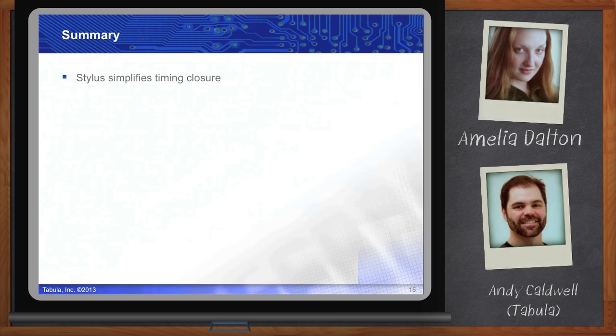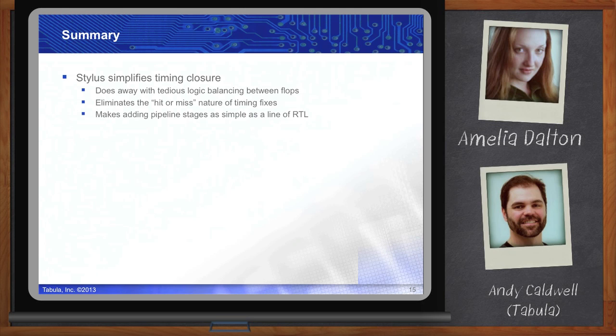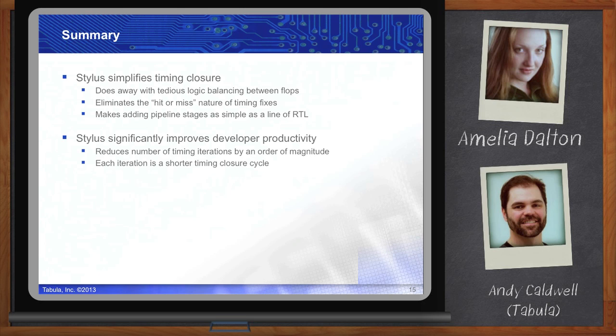Yep. Stylus significantly simplifies the timing closure process by doing away with the iterative, tedious process of delay balancing between registers, and makes adding pipeline stages or other latency changes very trivial. Great. Significantly improving developer productivity and shrinking the timing closure loop.